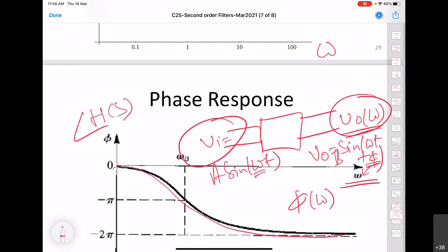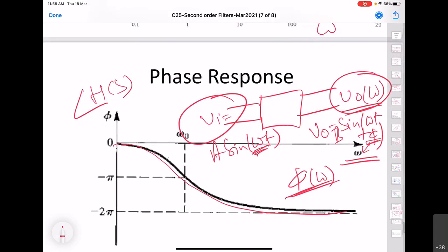There are certain media, called dispersive media, which introduce different phase based upon the frequency of the incoming signal. Those signals are then required to pass through another system which will neutralize the phase gain that the various frequencies have obtained when passing through this dispersive medium. So we will put another system at the output of this. Here we will put an all-pass filter so that whatever phase gain they have obtained here can be neutralized by making them pass through an all-pass filter with certain phase characteristics.